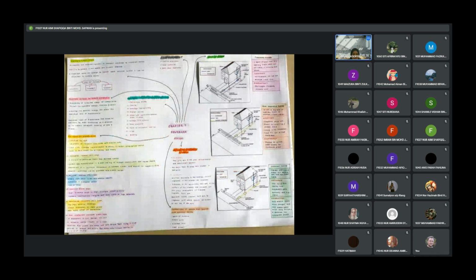We are now at chapter 5, Sewerage System. In this topic, we learn about function and significance, selection criteria of sewer material, the types of sewer pipe. There are 6 types, which are vitrified clay pipe, asbestos cement AC pipe, PVC pipe, concrete sewer pipe, reinforced concrete RC pipe, and lastly is non-reinforced concrete sewer pipe.